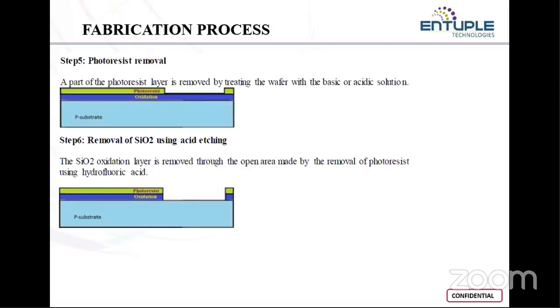So that's what you have done till now. You have printed that circuit on the copper surface with heat, and then you remove the unwanted copper by immersing that PCB board in a solution of ferric chloride. The ferric chloride removes the unwanted copper surface. The process of removing is called etching. And we just have that printed circuit alone. So that is the process we have done till now.